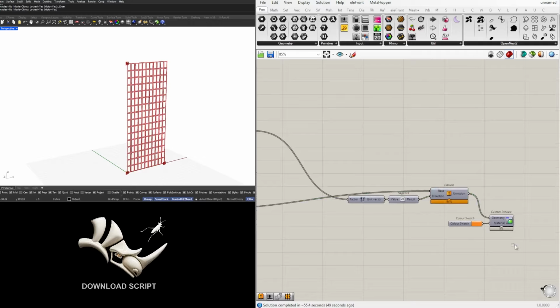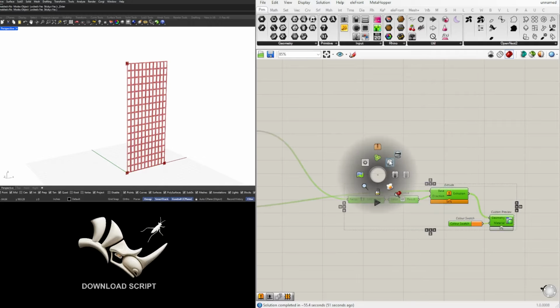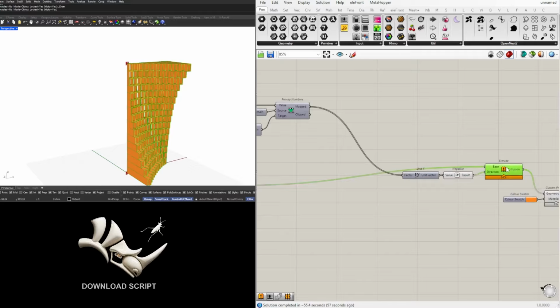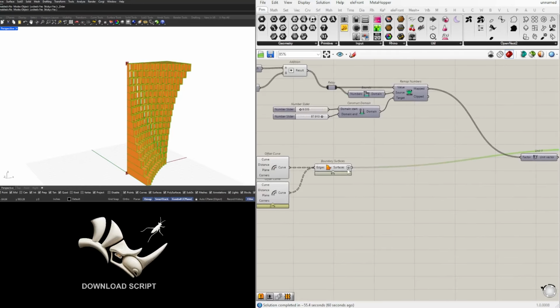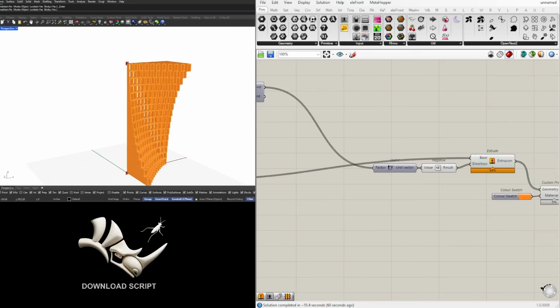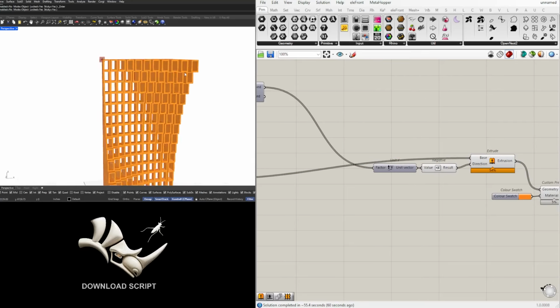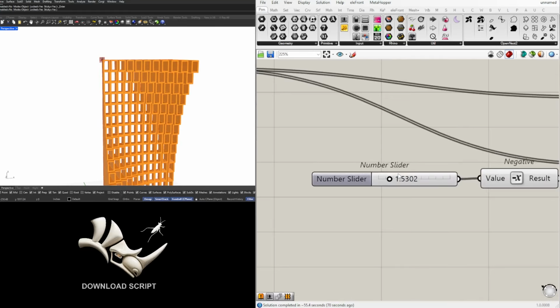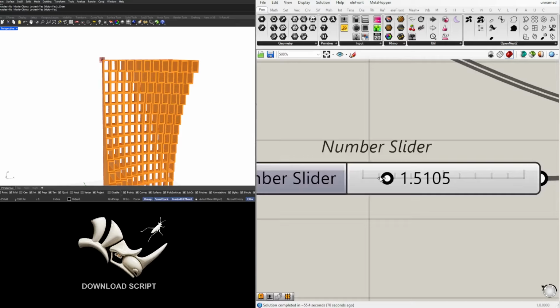And now when we bring this back, so before you even plug this surface into the extrusion, before the extrusion was a flattened set, so it was fine. But since it was grafted, it was causing issues. So flatten the output, plug that in. And notice that now it's using that frame that we created, which is here, to create the extrusion.